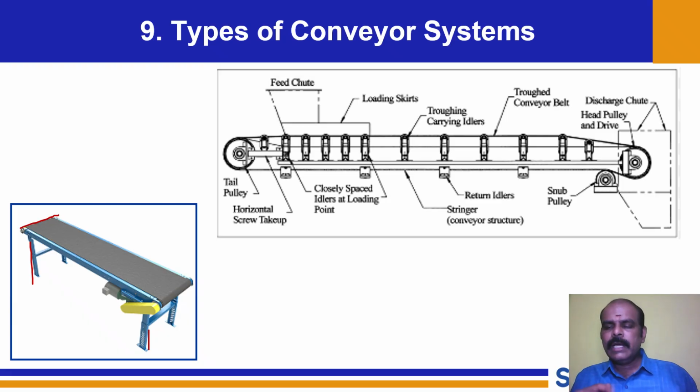Now comes another doubt. If you tension the belt, that is, if you provide some sort of pulling force, it is prone to some sort of damage over a period of time. Not on day one, but over a period of time, yes, it is susceptible to damage. So that is how we go ahead with different supporting idlers. We can go with an idler mechanism. Therefore slack can never be experienced in a conveyor. And the other thing is, we have a completely rolling one. So it is not going to be idle, it is going to be rolling.